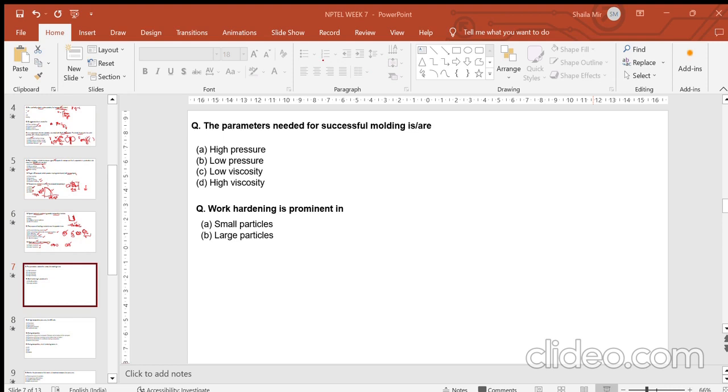So you have to remember that you might be compromising the density if you add some other material in a larger proportion. You have to modulate how much is to be added and in what weight fraction, like what is the weight fraction of addition and what is the density of that material. This will help you to calculate the theoretical density for a compact or a material that you have mixed. So I think this is for today.